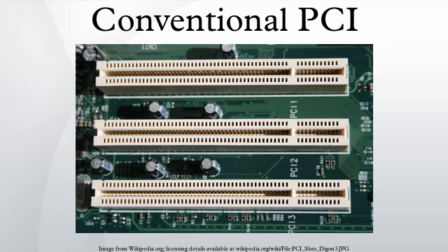Cache line toggle and cache line wrap modes are two forms of critical-word-first cache line fetching. Toggle mode XORs the supplied address with an incrementing counter. This is the native order for Intel 486 and Pentium processors. It has the advantage that it is not necessary to know the cache line size to implement it. PCI version 2.1 obsoleted toggle mode and added the cache line wrap mode, where fetching proceeds linearly, wrapping around at the end of each cache line. When one cache line is completely fetched, fetching jumps to the starting offset in the next cache line.